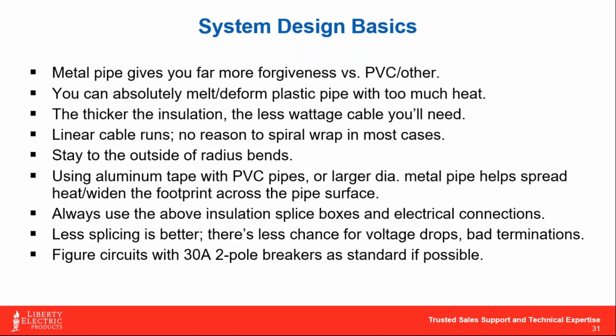Things like using aluminum tape with PVC pipes, that's a great idea. That helps dissipate that heat, helps reduce the potential threat of having a hot spot, or something where you could have a potential for melting. And the other thing that aluminum tape does really well is when we're talking about larger diameter pipes, let's say something like a 12-inch pipe, be it steel, it really doesn't matter what the material is. Your heat trace cable is really only going to be about a 1/2 inch to 3/4 of an inch, more like about a 1/2 inch wide.